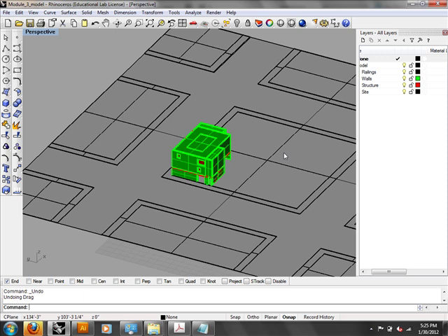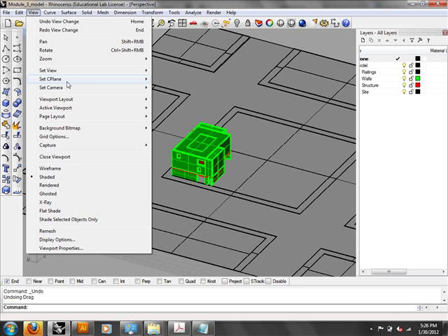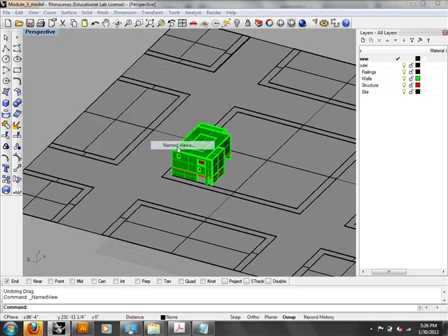Okay, questions, and then I'll talk about layout. Whenever you're doing multiple make 2Ds to do an exploded axon, would you just copy the building, delete everything from the first and third floor if you're doing the second floor? We'll probably hide it. I wouldn't delete it because then you'd have to undo all that stuff. But you could certainly, from this view, save this camera view. That would probably be a smart thing to do.